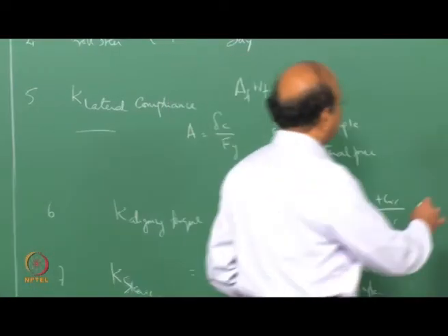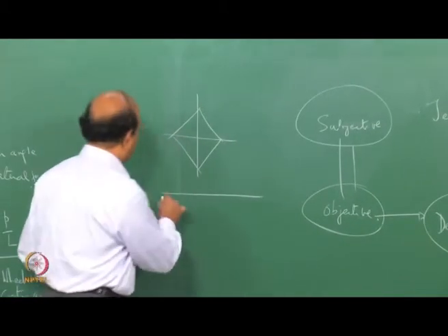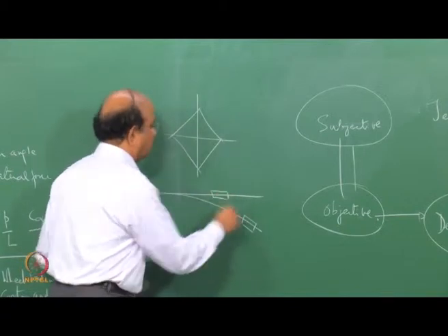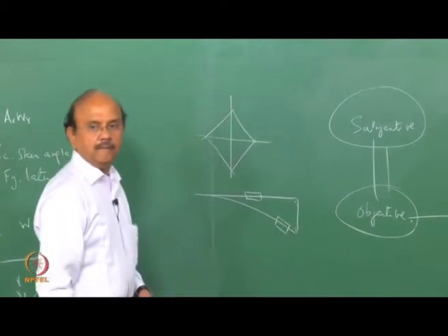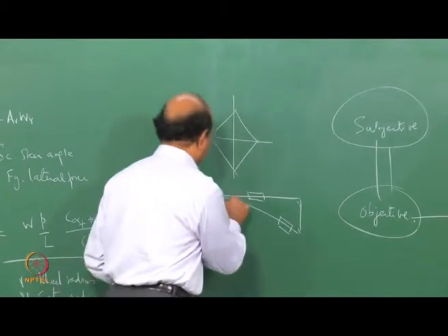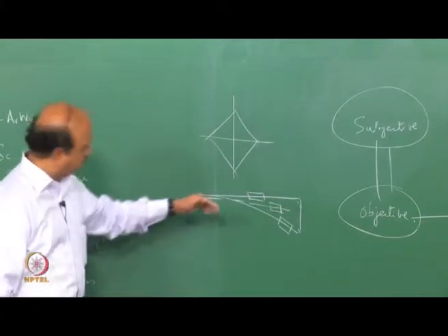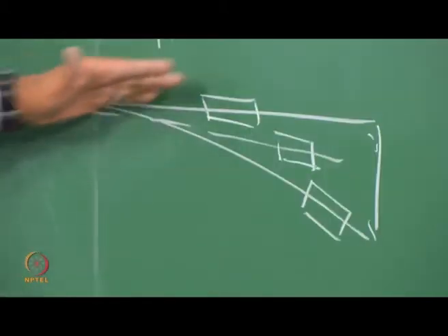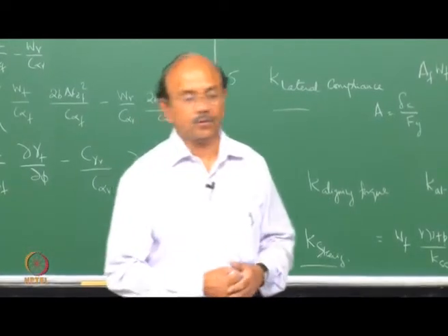If there's a pull, the vehicle that is going straight may go like that, and that's drift. But the vehicle can also go like this. What's the difference? Here it can turn like this. This is the pull. This can be drift of the vehicle as you go down. It may be due to the steering system and so on.